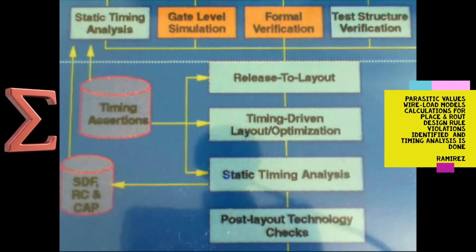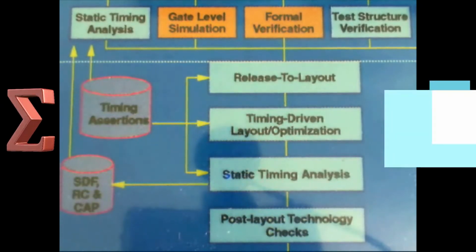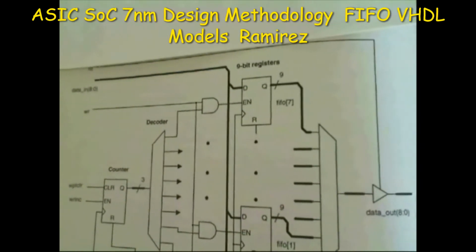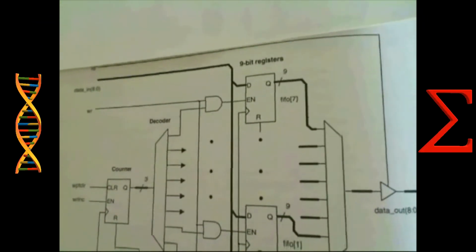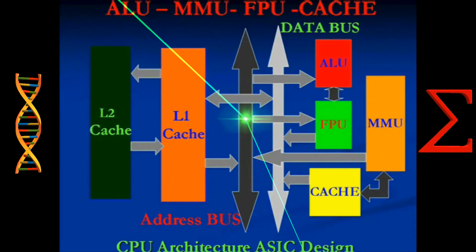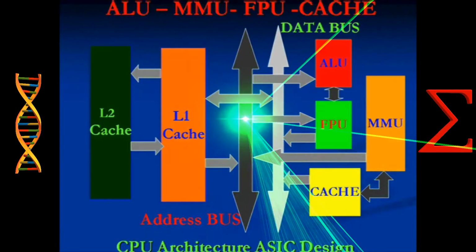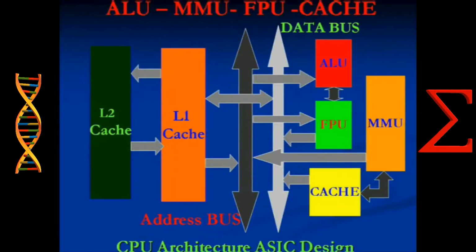And the system interface characteristics include input drives, input and output loads, and fan-out loads. The environment model directly affects the design synthesis results. So in design compiler, the model is defined by a set of attributes and constraints that a design uses, using specific DC_shell commands.